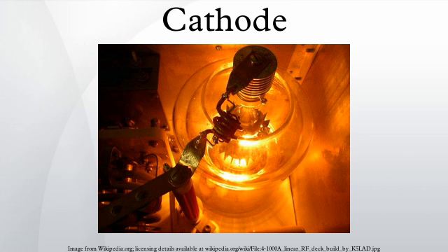Cold cathode: this is a cathode that is not heated by a filament. They may emit electrons by field electron emission, and in gas-filled tubes by secondary emission. Some examples are electrodes in neon lights, cold cathode fluorescent lamps used as backlights in laptops, Thyratron tubes, and Crookes tubes. They do not necessarily operate at room temperature.